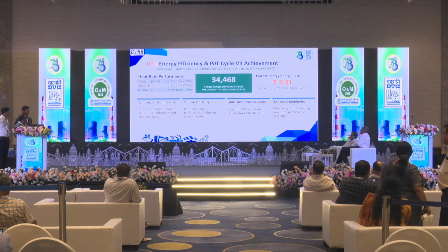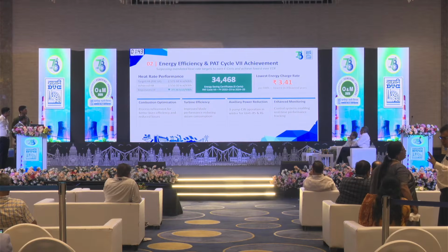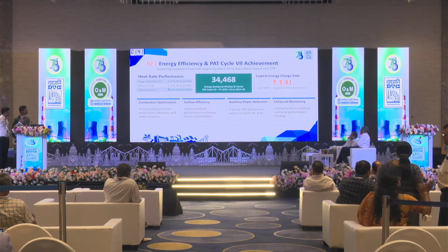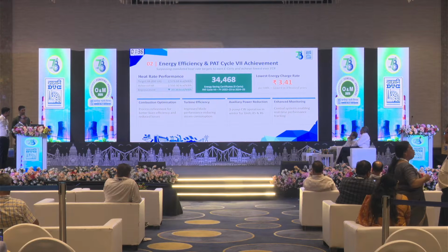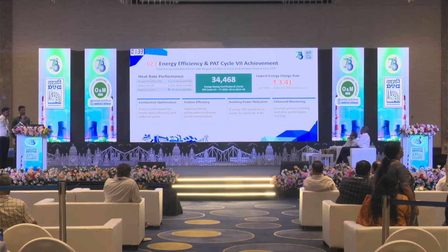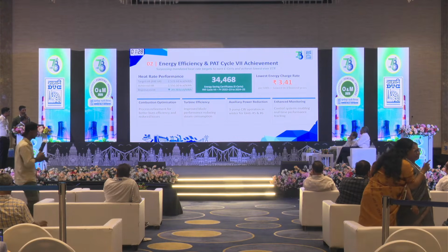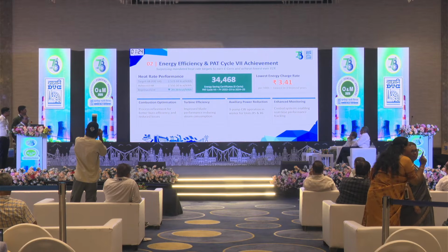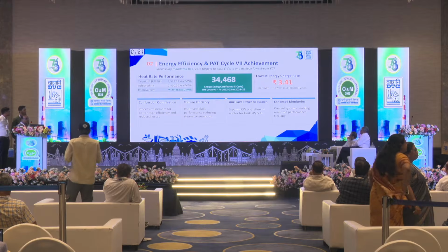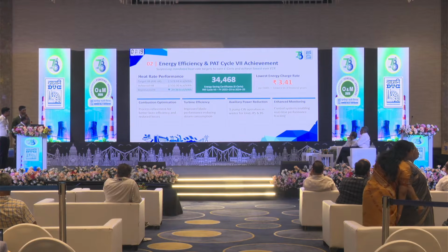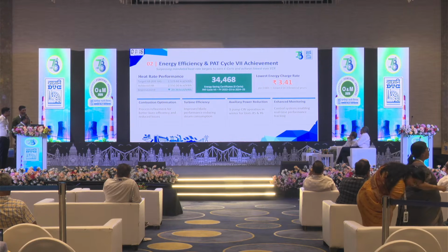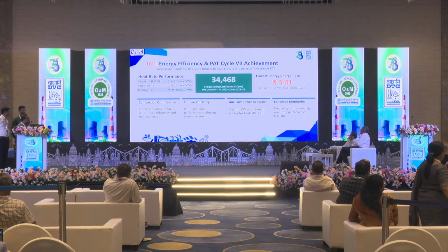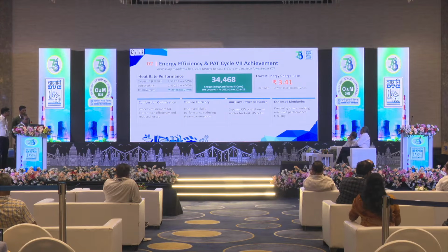The main optimization was in process refinement, boiler efficiency, and reducing boiler losses. On turbine efficiency, in Unit 3 and Unit 8 we changed the HPT module, which improved HPT efficiency and reduces the heat rate. On auxiliary power consumption, in Unit 5 and 6, 3 CW pumps are running mostly in the winter season, whereas previously 4 pumps ran, so it reduces the APC. Similarly, we are enhancing the control system by real-time monitoring of critical parameters.